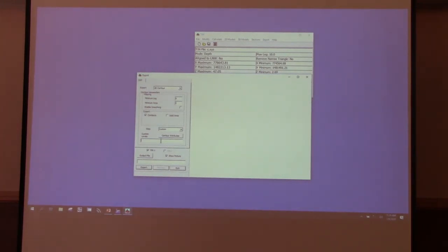You can specify the contours. I want one at 3, and one at 9, and one at 12, and one at 18, just because, and my numbers don't make sense there, 18. By putting a space in there, it's going to generate contours at those levels, which is very nice. It's a very nice way to do it.